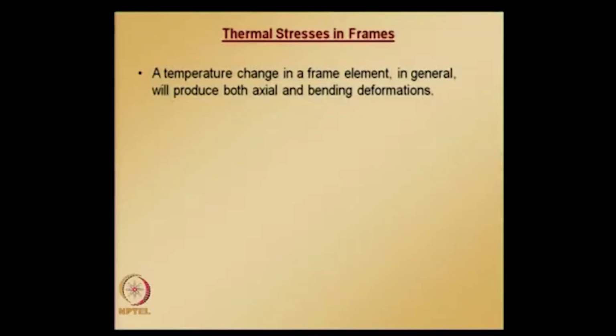So here in frames, in addition to this bending moment, again no shear forces will be there even in frames, and if it is a plane frame, because of these temperature changes we are going to have axial force effects as well. That is what we are going to see in today's class. So temperature change in a frame element in general will produce both axial and bending deformations.